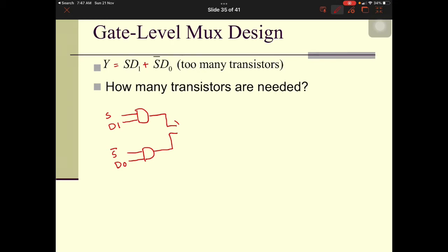This is the AND gate and this is Y. Okay, we break them down further. So as you can see here, between S and S bar, there should be an inverter. You need an inverter over here, so this will become S bar, right?